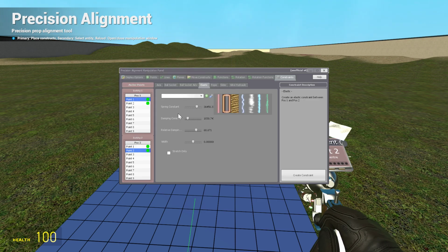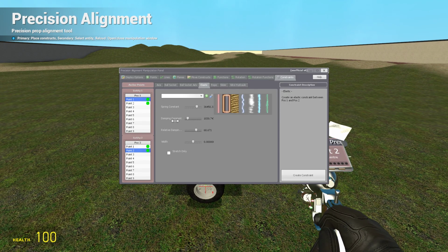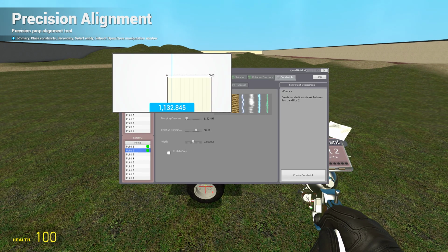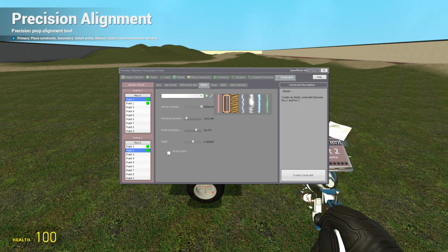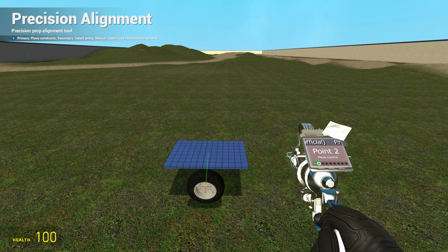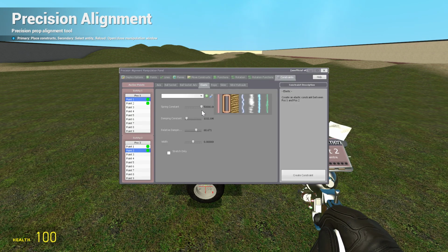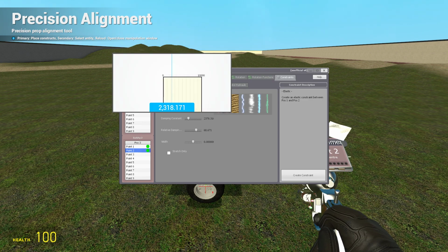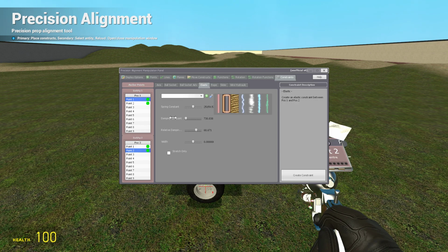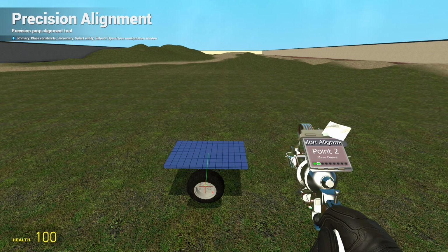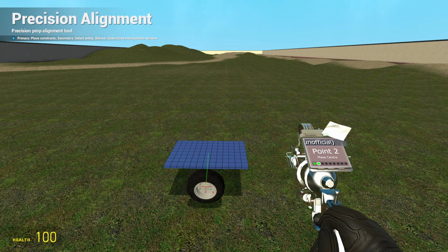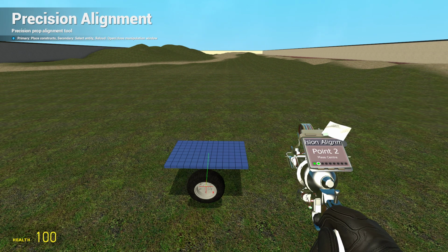And now, if you want to make very stiff suspension that's bouncy, you would do something like around 1,000 here, and then obviously 15 or 50,000 here. Now, if you want to make something very soft, very elegant suspension that's able to ride over jumps well, you would lower this, and lowering this kind of allows it, I guess you could say, to stretch more. It takes a lot of the pressure off and spreads it out. So you could have a higher damping here, and you'd be able to get very soft suspension that rides over jumps perfectly like that truck I just had out.